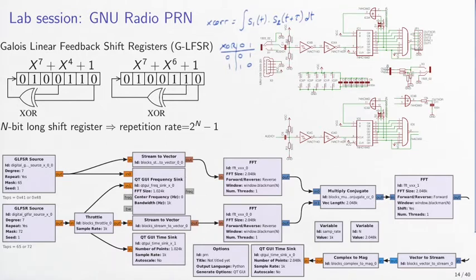If, however, the two sequences match, we see that 0 and 0 will create 0. All 1 and 1 matching will create a 1 XOR 1, which will create a 0, and all values will add up as 0. So we have this multiplication here, which is taken care of by this XOR function. If pattern 1 and pattern 2 match, then all the 0s will match with 0s, creating an output at 0. All the 1s will match the 1s with an output at 0, and the output of this multiplication of all the terms will be all zeros.